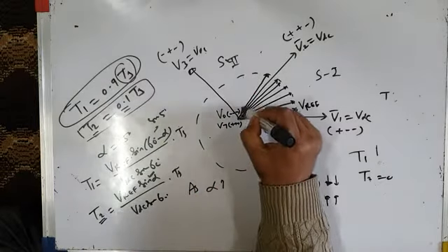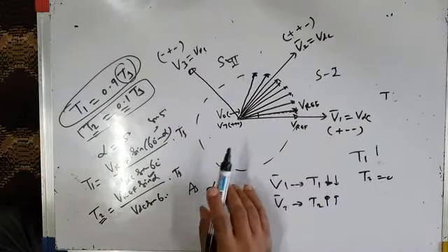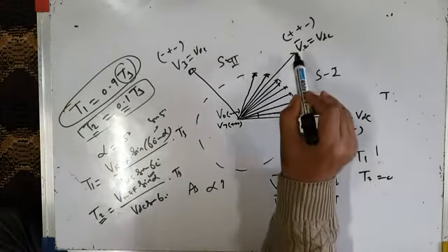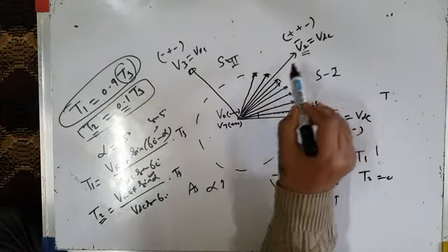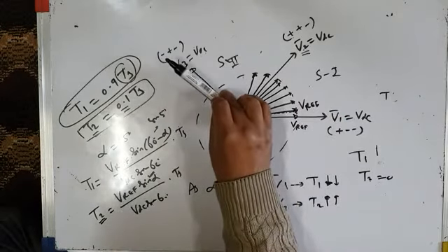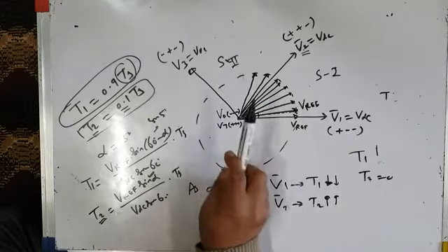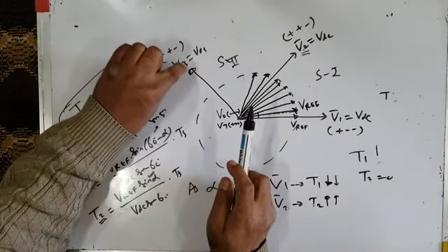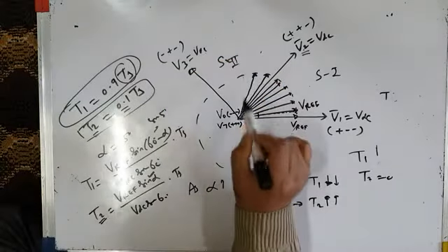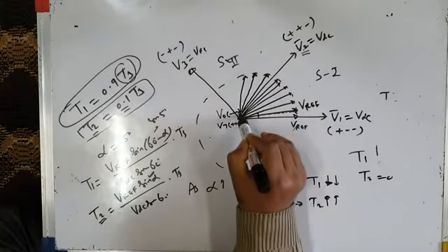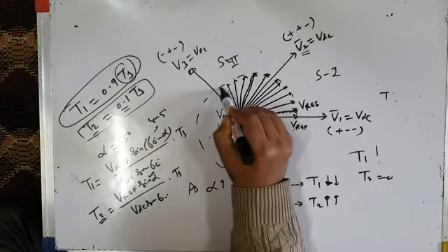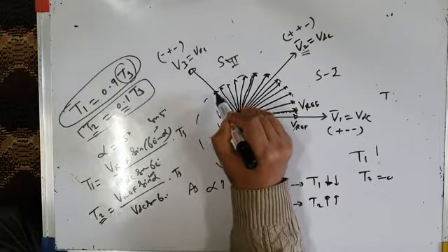तो थोड़ी देर के बाद अल्फा इंक्रीज हो जाएगा. As alpha increases, T1 will decrease, T2 will increase. That is the time interval for which V2 voltage vector is applied across the load decreases, and the time interval for which V3 voltage space vector is applied across the load increases. तो ये वेक्टर ज़्यादा देर के लिए लोड के अक्रॉस अप्लाई होगा, ये कम, so it will pull the reference vector towards itself, and then as alpha increases, your reference vector will keep on moving towards V3 till it aligns along V3.